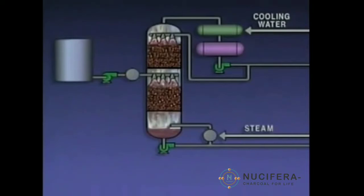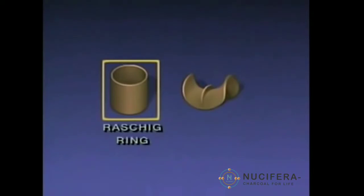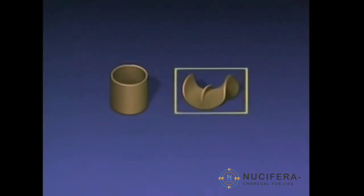Another type of tower, called a packed tower, contains layers of devices called packing instead of trays with bubble caps. There are many different types of packing. Some towers have sections that are filled with cylindrical rings like the one illustrated here. It's known as a Raschig ring. Another type of packing is known as a Berl saddle.